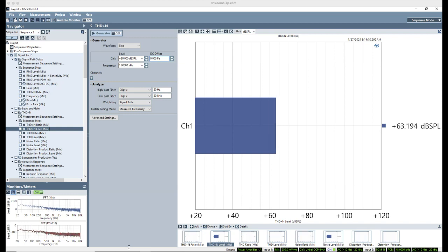The more common thing to do is to not measure harmonic distortion. It's to measure intermodulation distortion and to stimulate the microphone with 2 speakers, each generating 1 of the component frequencies for an IMD measurement. Little tight on time here, but feel free to email us and we can walk you through that procedure.